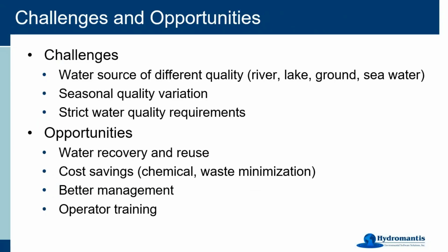If we look at the challenges and opportunities in this particular field, first and foremost, the challenges are that, working on different projects, we have seen that there are different sources of water, and the source water qualities could be very different from each other. The challenge it presents is that you have to find the right ways to treat the water in different mixes, or when you're shifting your water sources from one source to another, you have to make the right adjustment in your water treatment plant. Also, the sources could change in seasonal quality. There could be some seasonal quality variation as well.